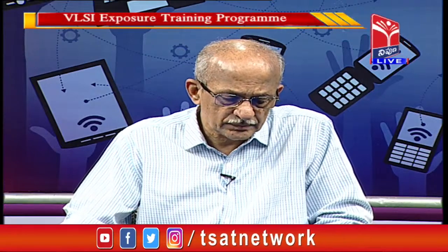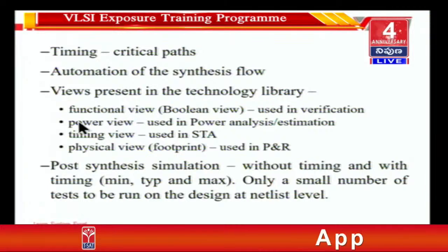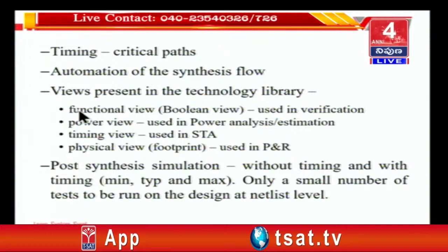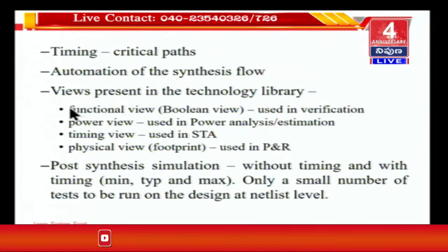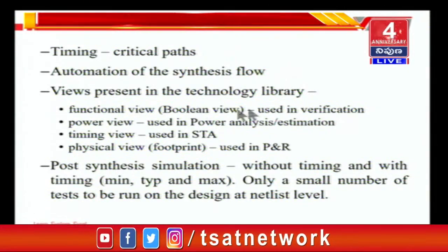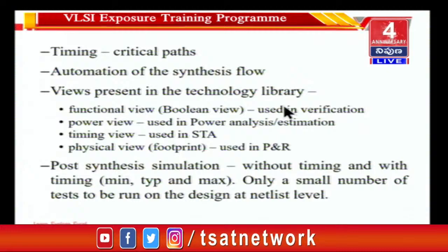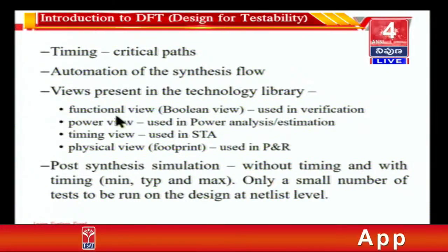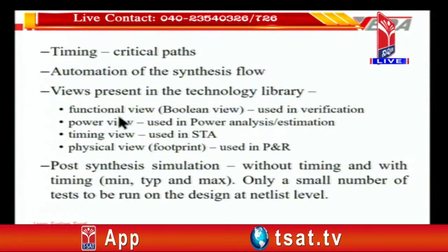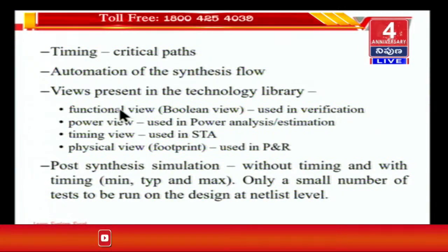Then the technology library itself will have several different views or several different functions inside it, and these are used at different points of time in the manufacturing flow. The first view or the first information, data, whatever you call it, many people prefer to call it a view, is the Boolean view used in verification. Boolean view means if you have a 2-input AND gate, it will say that the functionality of this 2-input AND gate is Y is equal to A and B. Simple as that, Boolean view, without giving any other information.